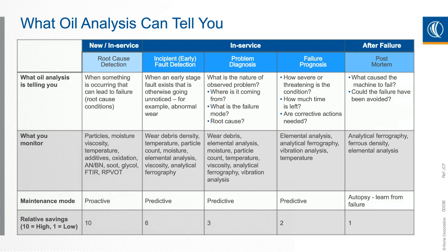So if it's an incipient early fault detection stage, then you may be seeing abnormal wear in your oil analysis, but really you're not seeing much else happening on the machine. Maybe the viscosity hasn't changed, or maybe the vibrations haven't changed, and everything else seems to be normal, but there's wear debris showing up. If you can figure out where it's coming from and what the failure mode is, or even see what the root cause might be, then you're able to develop a problem diagnosis, and you're going to be going into a little more detail with your oil analysis.